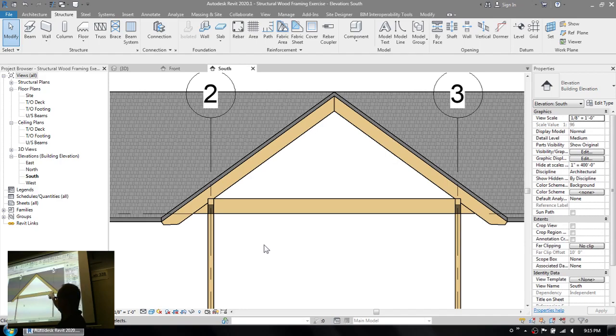And then you've got your heavy beams, which support the rafters, which in turn support the deck that's on top. So the process by which you do one of these expressive structure projects is get that roof sorted out, figure out where your column placement is, get the beams in place, and then you can start drawing your rafters on top of the roof or using the roof as a guide.